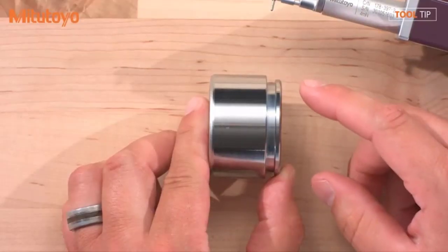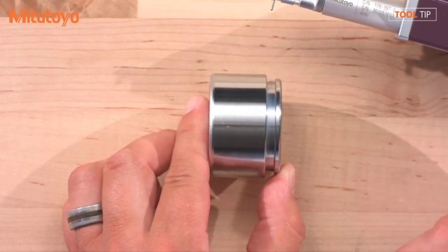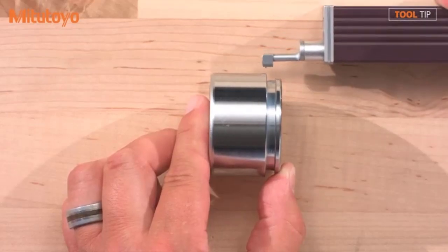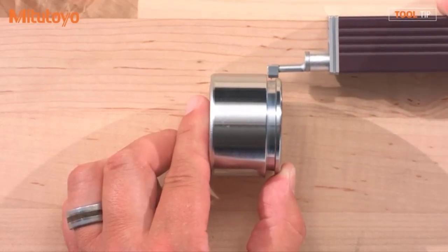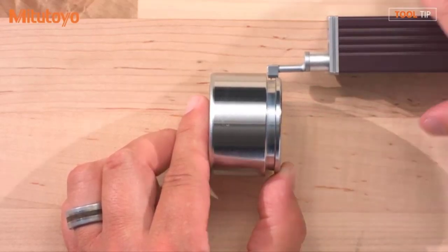Drew, that makes sense, measuring round parts versus straight parts. Are there any other features that would lend themselves to a skidless device versus a skidded? Absolutely. So let's switch parts for a second. Now we're going to take a look at a piston. Notice the piston has a small groove here on the outside diameter. If we wanted to measure this groove, it might be a little difficult to do with a skidded system because as I start to move my stylus in, you notice the skid is larger than the groove that I need to measure. So I could not actually measure the bottom surface of this groove with a skidded unit.